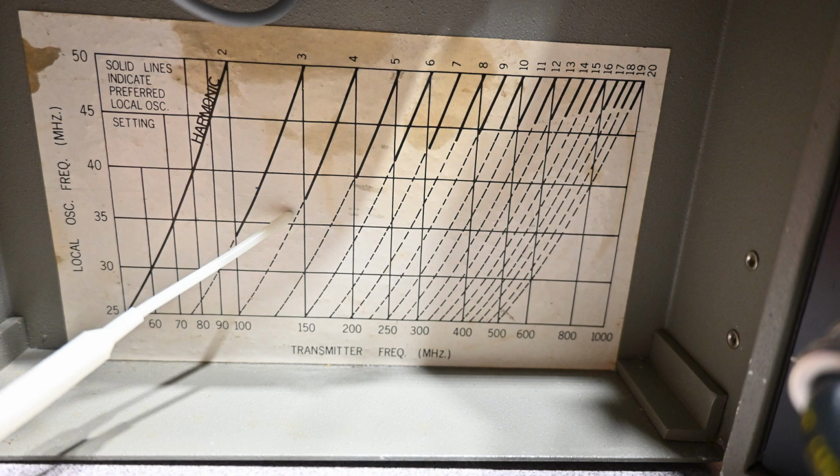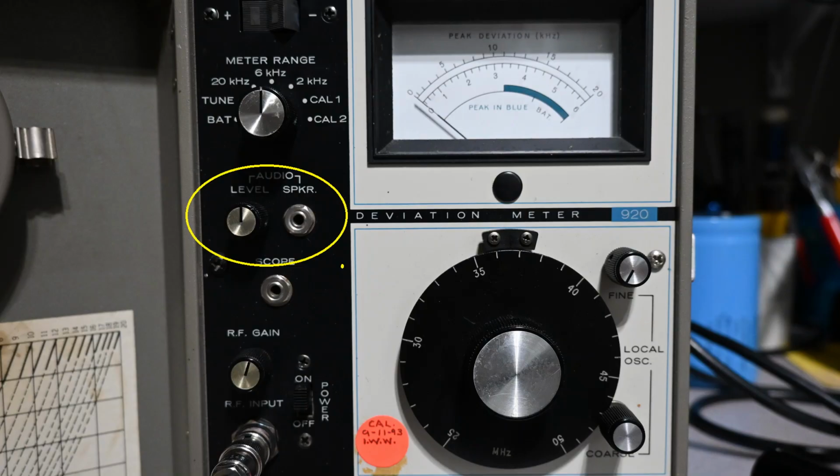On the inside front cover of our instrument, under the 8 ohm speaker, is a chart spelling out the harmonic relationship tuning of the instrument to provide its coverage between 25 megahertz and 1 gigahertz. Sensitivity is 25 millivolts at 25 megahertz, dropping over its tuning range to 50 millivolts at 500 megahertz, and then decreasing as anticipated from there. The instrument features a local speaker jack and volume control for de-emphasized audio, and the cover has an 8-ohm speaker and plug for it.